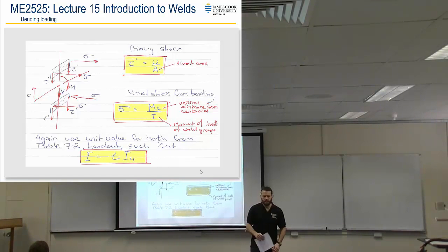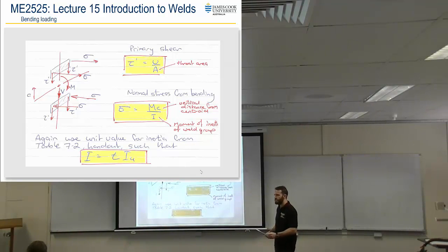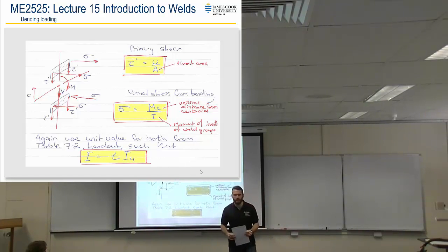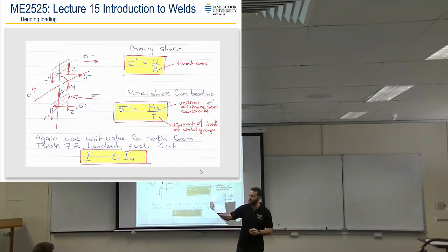Now, you guys will all remember from the classes where you've learnt about moment of inertia and things like that, that torsional, so polar moment of inertia, doesn't matter what orientation the shape is because it's round in a circle, so you have the same value regardless of your orientation. But bending moment of inertia is different if you are bending up and down as opposed to side, yeah? So bending on a channel this way, down, is very different to bending on a channel this way, down, in terms of the moment of inertia. You have different moment of inertia in each direction.